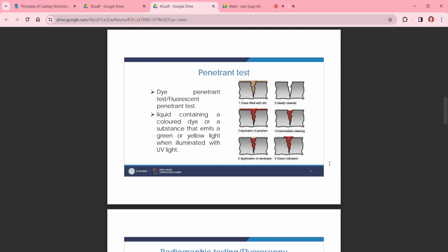And for analyzing the defects inside the castings, like if air inclusion is there, due to that air inclusion some bubble formation will be created inside your casting. Inside that bubble, there will be no material. Whenever you apply that casting in some application and provide some force on that material, that bubble will create resistance up to some extent.